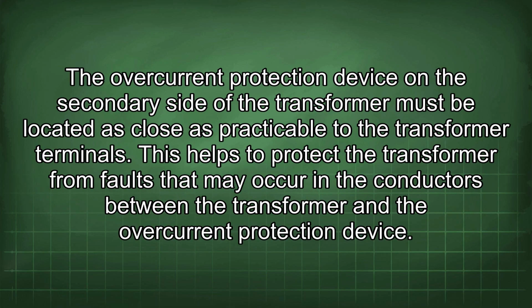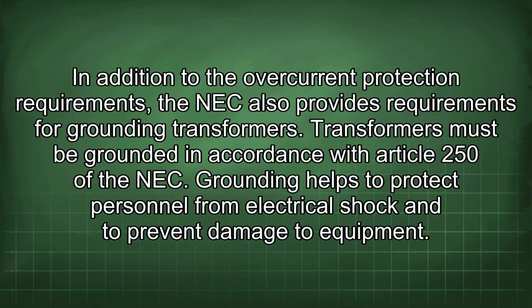The NEC also provides guidance on the location of the overcurrent protection devices. The overcurrent protection device on the secondary side of the transformer must be located as close as practicable to the transformer terminals. This helps to protect the transformer from faults that may occur in the conductors between the transformer and the overcurrent protection device.